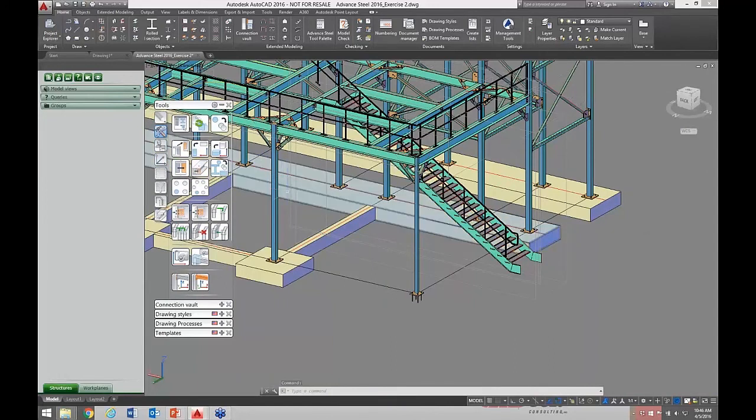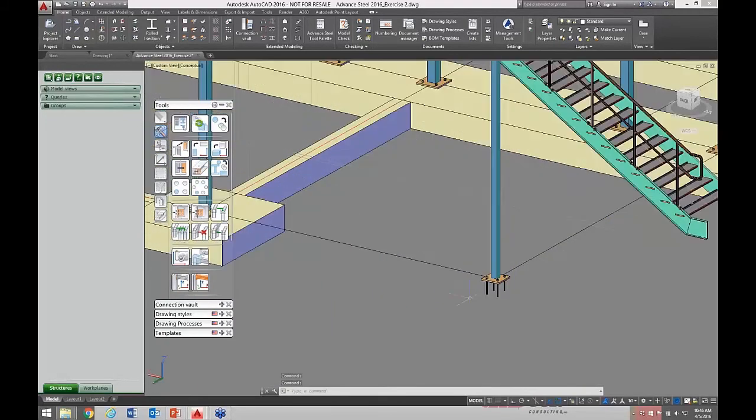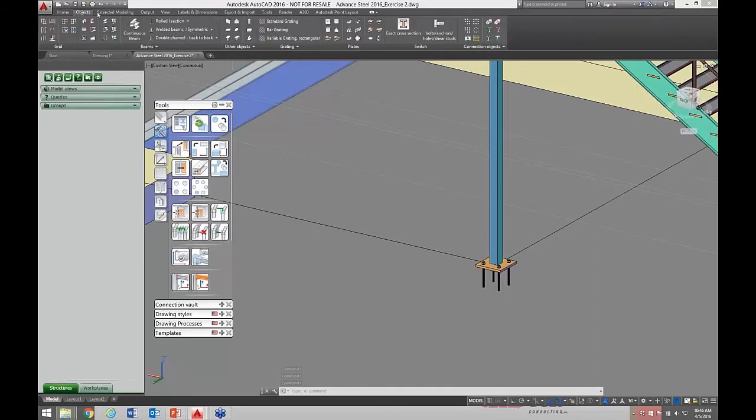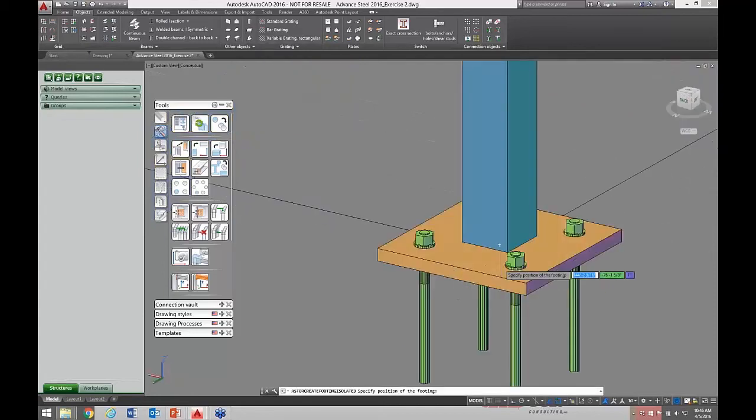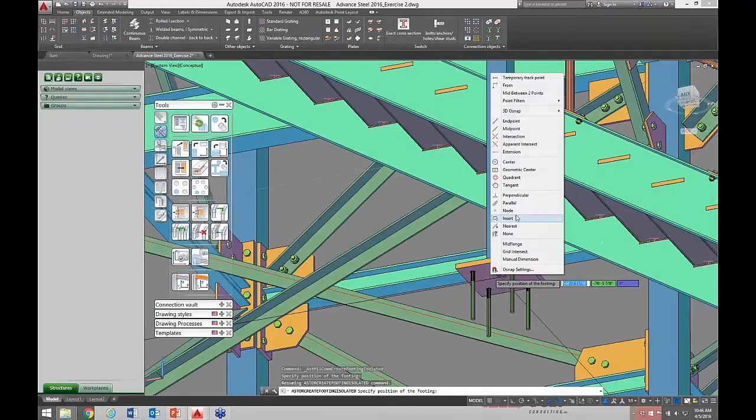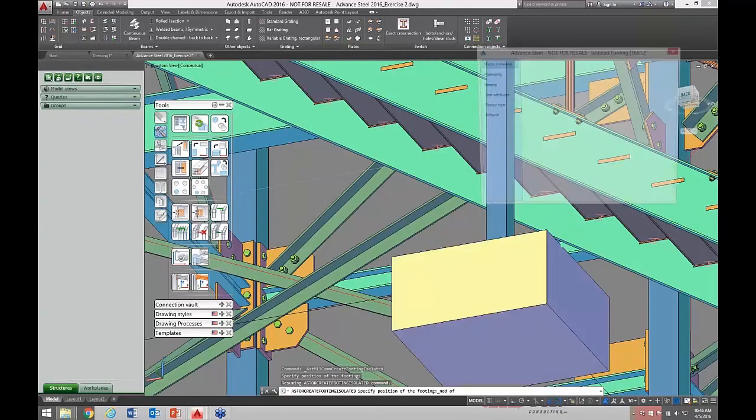for that item. All right, I mentioned something about some foundation elements. Sometimes we need concrete pieces. So let's go to our other objects here. Inside of this, we have the capability of doing concrete columns, beams, walls I had mentioned. We actually have continuous and isolated footings. I'm going to do an isolated footing at this point. And I already have a base plate on this one, but I'll go ahead and just snap to a node. We'll see a placement on there.